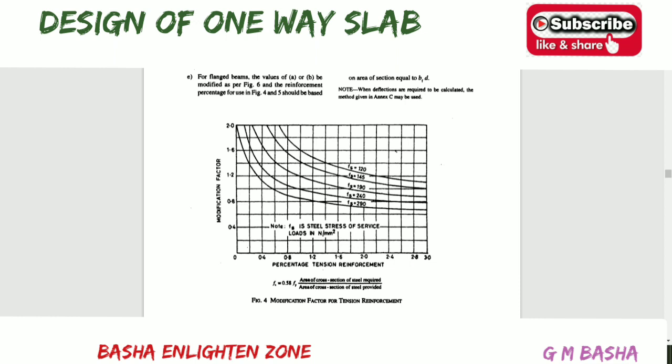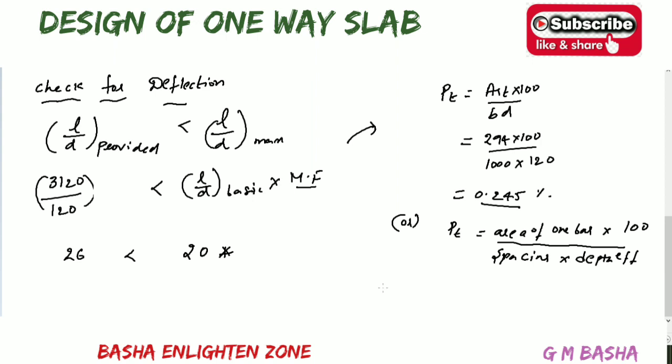Again, you can relate with this curve. For finding this curve there is one formula: Fs equals 0.58 Fy times area of cross section of steel required by provided. Generally for beams that value will be somewhat different. The area of steel required will be some 290, and after providing 3 bars of 10 mm diameter, that is 3 into pi d square by 4, you will get a different provided value. So you can check the ratio of that in beams.